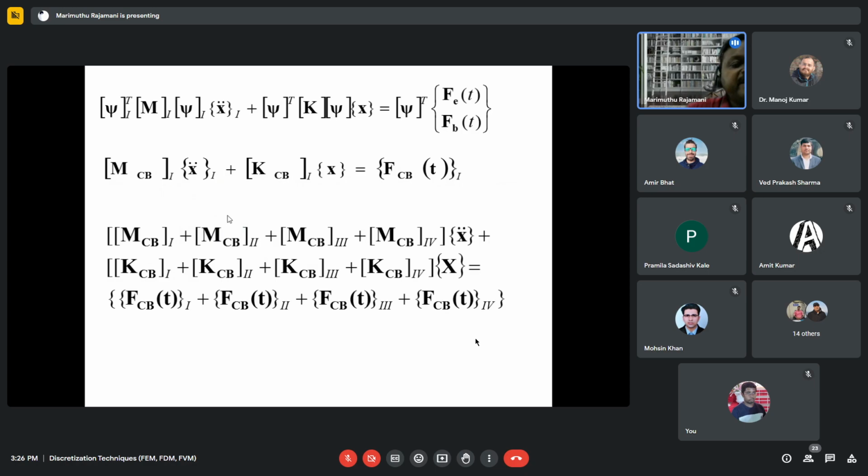They study, they design, they do everything there, and then they supply only the Craig-Bampton matrices corresponding to the interface nodes, where it has to be interfaced with the launch vehicle. That portion of the matrices is added, and then we study here the complete dynamic characterization of launch vehicle plus satellite.